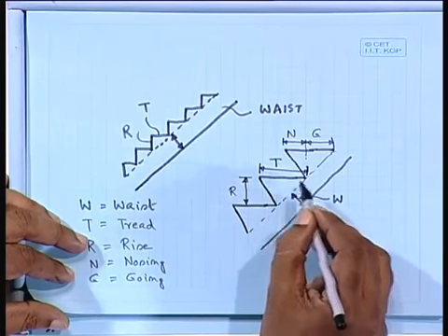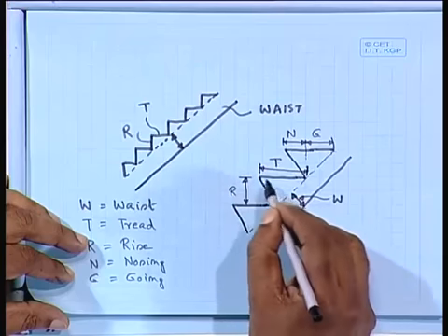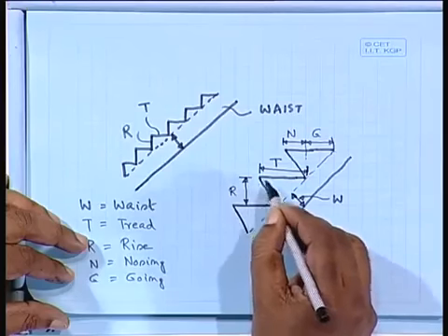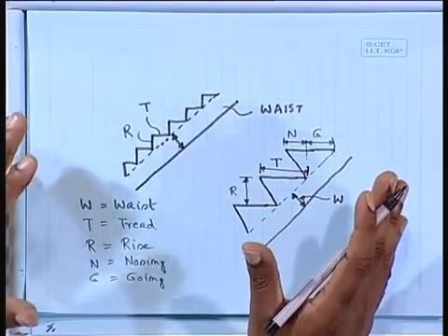But also, the length and the height, or tread and rise, should be somewhat proportional. You should note that in our subway at Kharagpur station, the steps are quite wider than the rise, and we really feel discomfort. So that type of proportion should be there, so that we do not feel any discomfort.